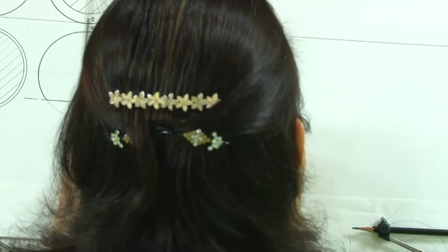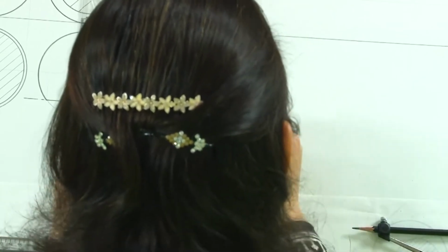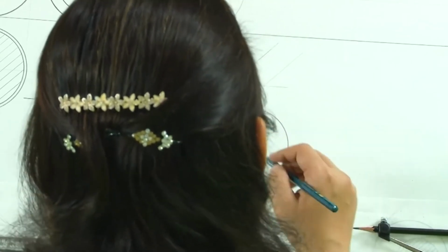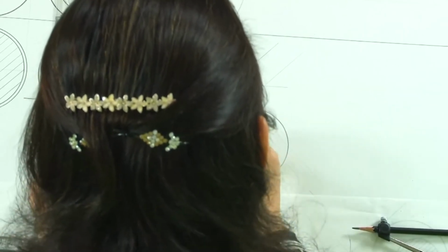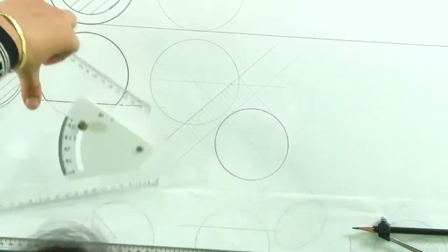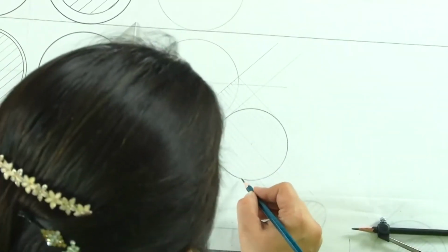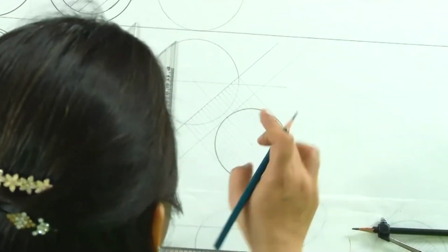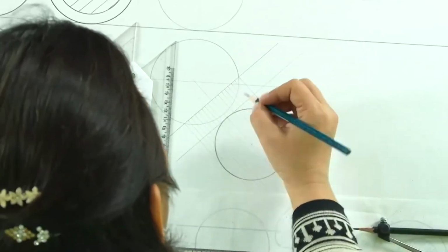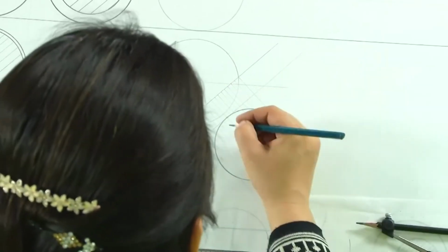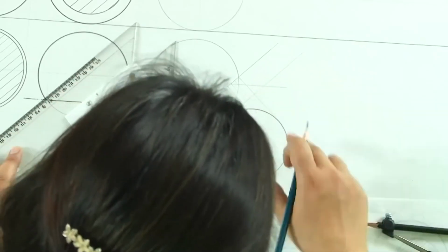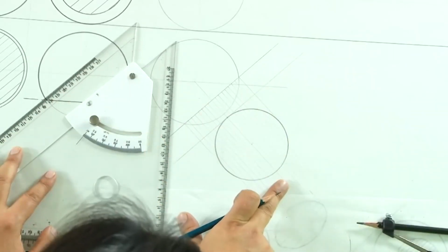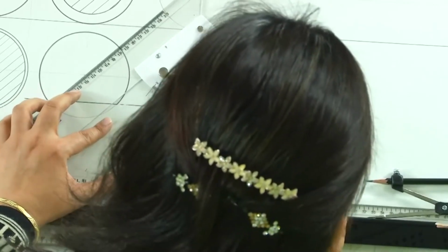So we've just reversed the process and now we are going to get the distances onto these lines in the front view. What we know is that these lines are being intersected at this and this distance. So this is the reference line. This is the distance which we are taking for each of these lines. Now we will take it up.